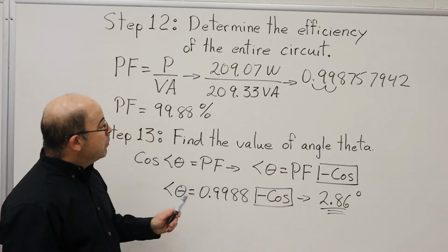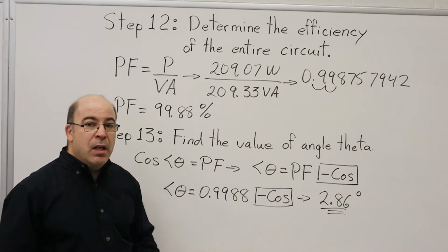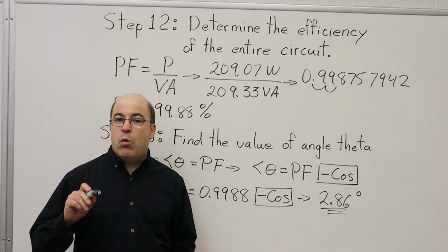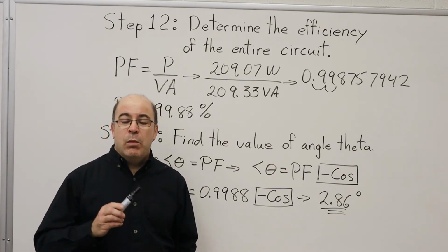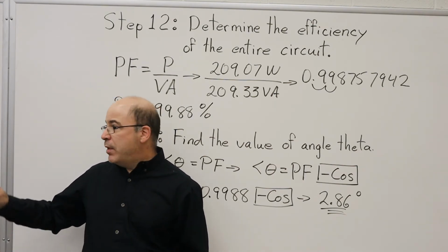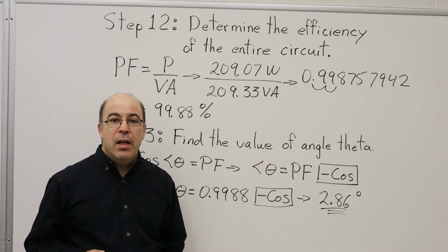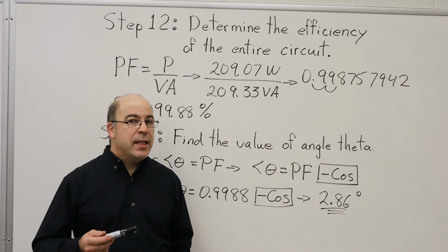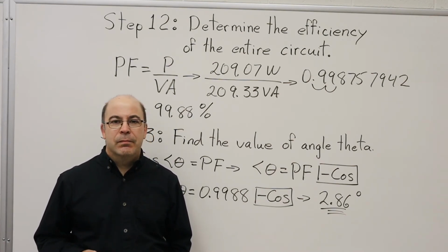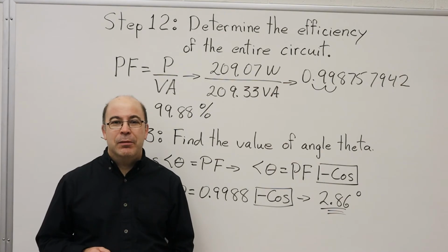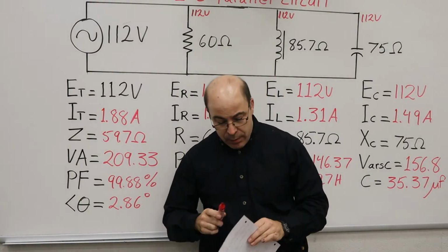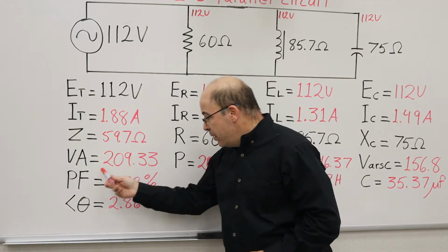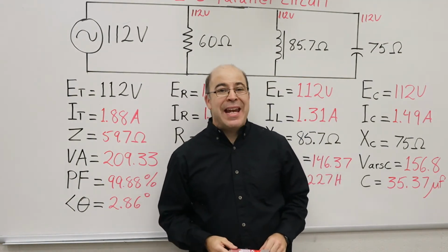Now, one of the things we're also going to have to do is determine the phase angle difference. Is the voltage leading or is it lagging? Well, what we're going to do is input these final values into the chart, and then we're going to have a look at that and figure out which way this is going. Is the voltage leading or is it lagging? So stick around and let's find out. I had mentioned that I thought the power factor was going to be very, very high, and I was very surprised, 99.88%.